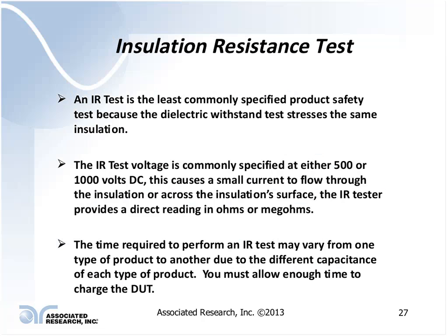Insulation resistance tests are normally conducted at 500 to 1,000 volt potential on most products that we as consumers use on a daily basis. Don't get me wrong, an insulation resistance test can be as high as maybe 10,000 volts, depending upon the type of product that you're testing. Typical high voltage applications may require a much higher insulation resistance test.